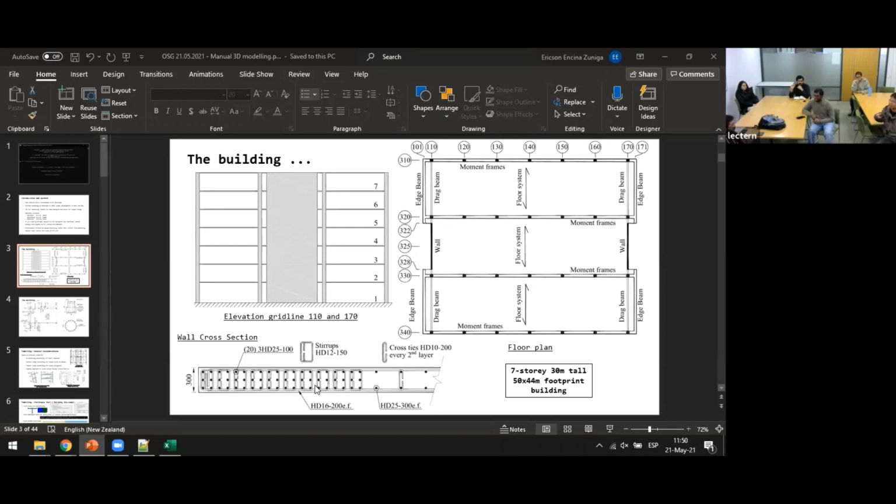Yeah, because the issue I referred to, what I did to solve it is I just changed the algorithm and it was solved. So I think sometimes that seems to be another instability. OpenSees is quite particular in that sense. It has happened to me that I run exactly the same model without changing anything in a different version, and it works. I don't know what it is. It should be the same. I don't understand. So you can change versions as well, to see if it works. Such a weird way.